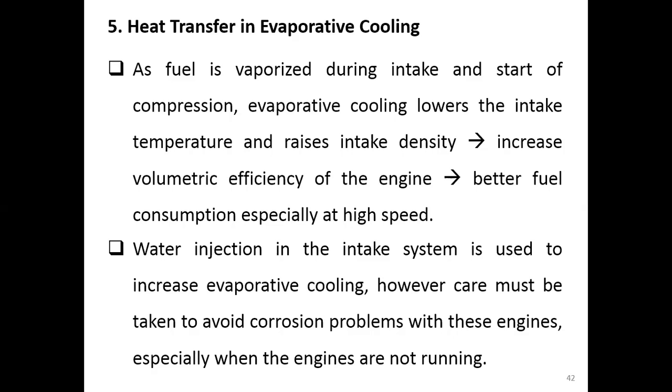Okay, so this happens naturally already, right? This heat transfer happens naturally when we operate the engines, in evaporative cooling. Now, if we want to increase the amount of evaporative cooling, we can do it by injecting water. We add water in the intake system.